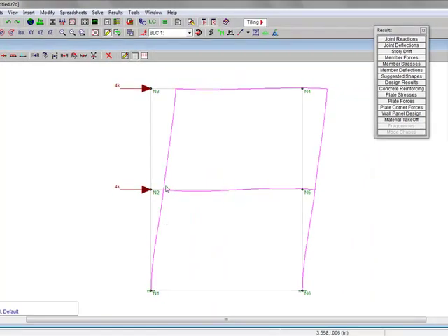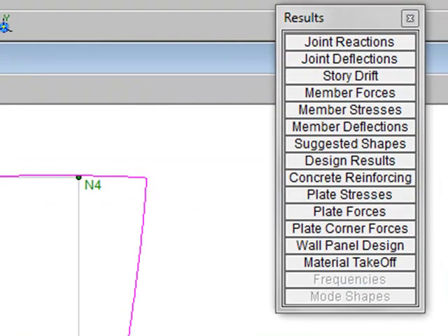You've got double curvature of the columns. We talk about that in structural mechanics. And the beams are also in double curvature. That looks like a pretty typical deflected shape for a lateral load. So it looks like I've set things up correctly for the moment frame.